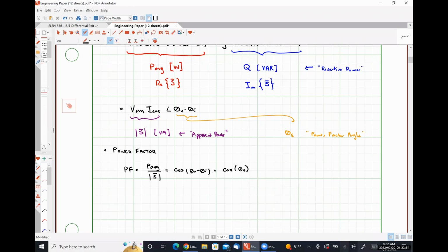When a load is operating at a power factor less than a magnitude of 1, it means the source is being required to generate more than the minimum amount of volt amperes necessary to supply the required average power needs of the load.